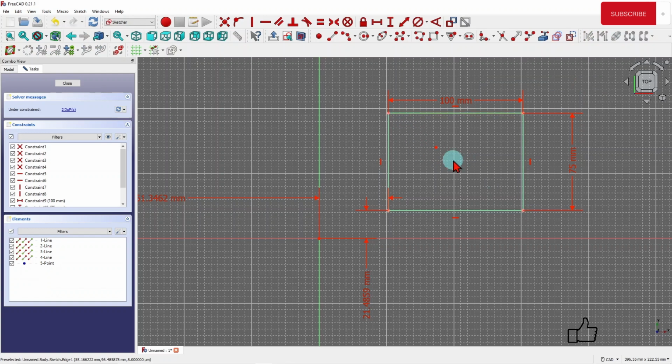Now I want to center it. So the best way to do this is the symmetric constraint feature. Pick this point, the vertices of the two rectangle, and pick this guy, and that'll put this one at the center because it's symmetric. This feature is symmetric to these 2 points. That's what it does. You can hover around this button and read what it is. It says create a symmetric constraint between 2 points with respect to a line or a third point.